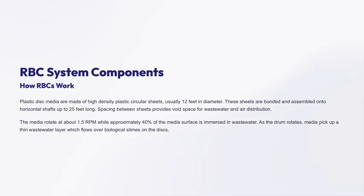Let's take a closer look at the RBC system components and how they work. The core of the system is the plastic disc media, which are made from high-density plastic. These discs are quite large, usually about 12 feet in diameter, and they are bonded together and assembled onto horizontal shafts that can be up to 25 feet long. The spacing between each disc creates void spaces that allow for effective distribution of wastewater and air throughout the system.